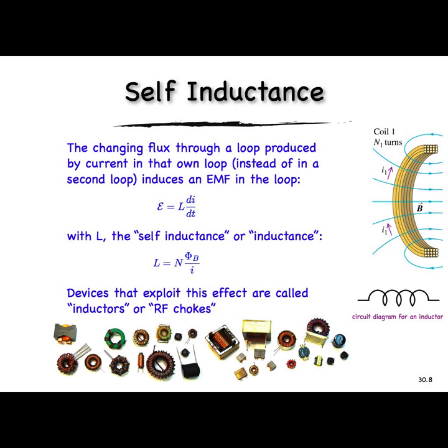And I can plug in some numbers. I'll plug in a 1/2 meter long solenoid with a 10 centimeter square area, so something like this, with 1,000 turns in one coil and 10 turns in the other. And I'll put 5 amps through at 60 hertz.